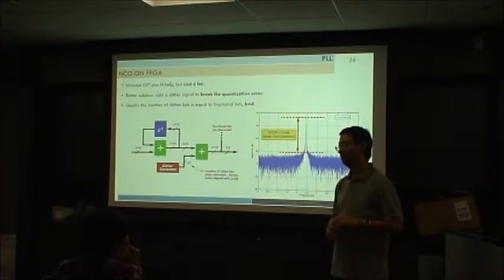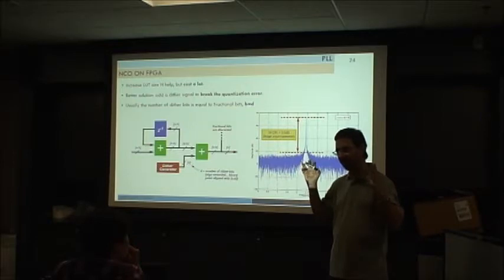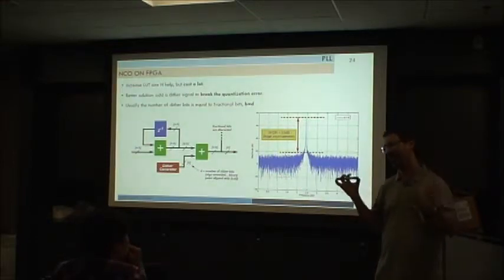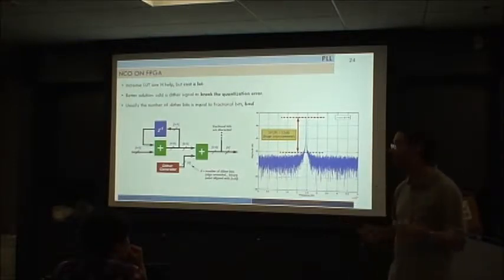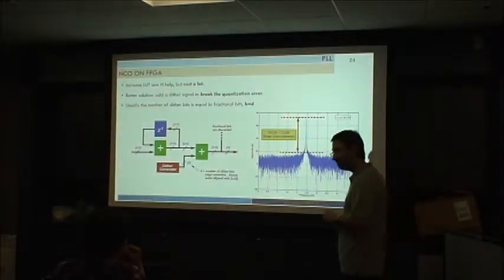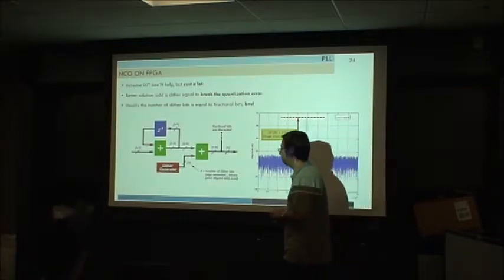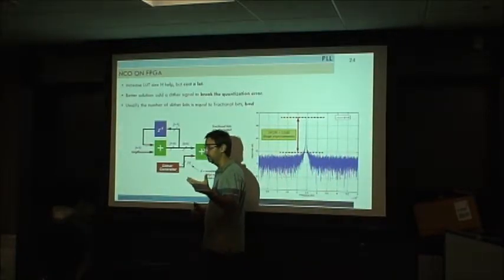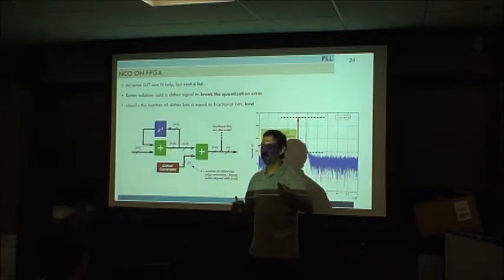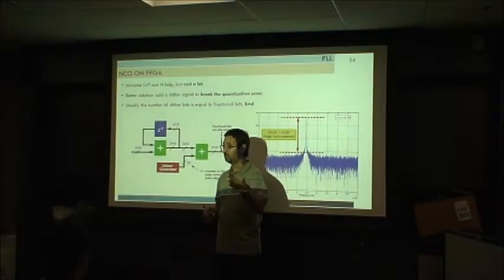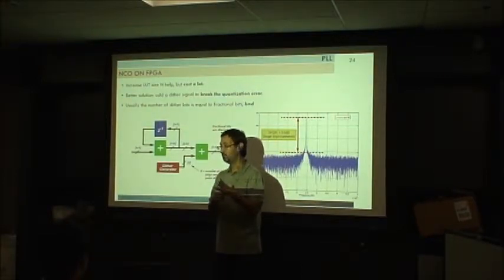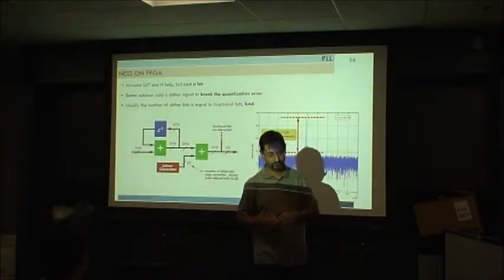No idea? You add noise. Sometimes you say, okay, I am adding noise, but I am improving this. How could that be? That's some weird stuff that happens when you add noise to the signal. So you break that pattern. Instead of reading 1, 3 every time, one time you will read 1, but the next time, because of the noise that you are adding, you will read 2. That is the one that you want to read. That is the idea.